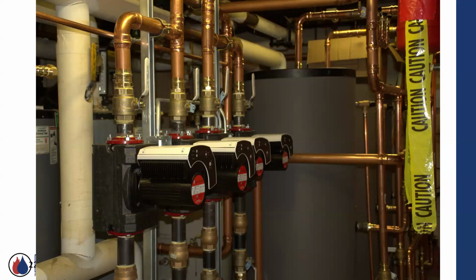We were just showing a quick picture someone took of an install, and kind of to Will's point, we're just going to jump into it right now. I have these two pumps, a certain size. You can see them plumbed together, so one distribution, so it's a standby pump. One's operating, one's standby. And that would most likely be the larger one that's probably going out to all the apartments upstairs, so whatever the load is upstairs. And then the other two guys, they're feeding domestic hot water tanks. So when there's a call for domestic, again, not a bunch of zones, it's going through a coil.